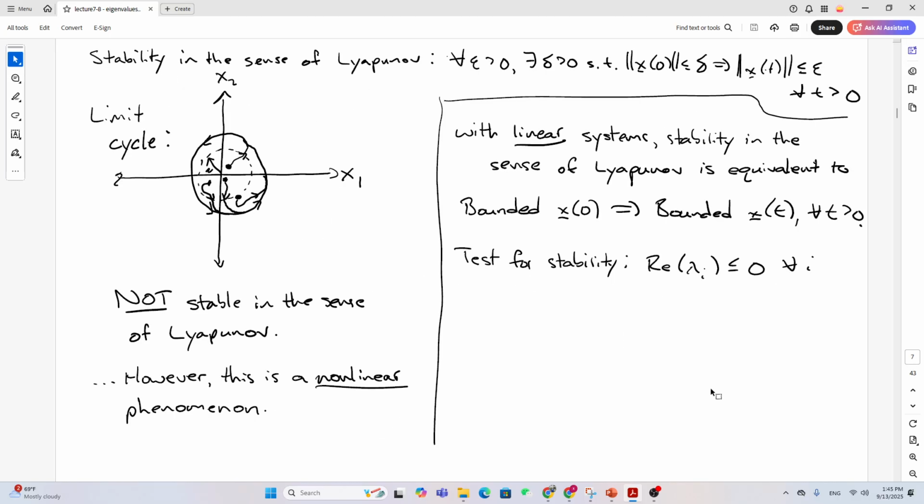Okay, so there are cases where Lyapunov stability will give you a different conclusion. Let's say you have a nonlinear system. I'm not going to elaborate a lot on this nonlinear system, but as we all know, in a nonlinear system you have multiple equilibrium points where you can have bistable behavior, right? A bistable system has two different stable states and can transition from one to another, depending on your initial condition. If your initial condition is slightly off the threshold, it can eventually be attracted to a different stable state, right?